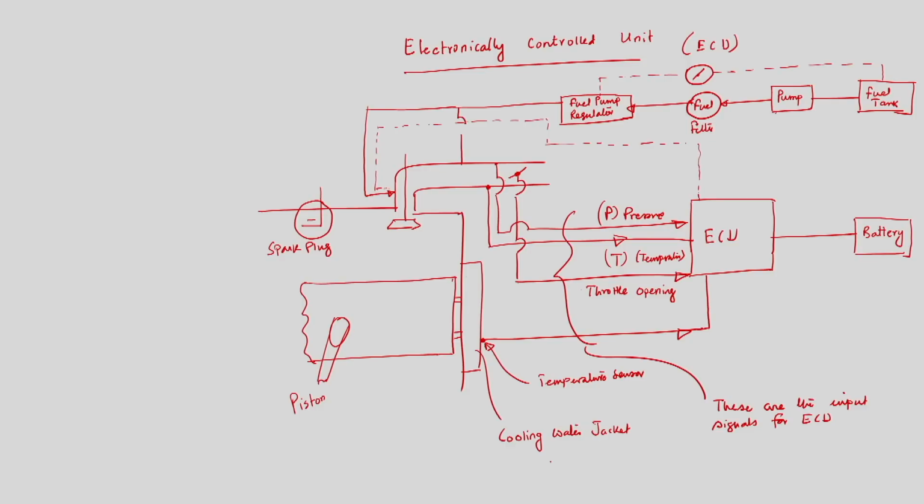Now, if you would like to supply fuel over here, again that information will come from the ECU. So, these are actually very important. What we have seen is that the amount of fuel that will be injected into the engine cylinder depends upon the load and also the pressure and temperature of the air at the intake manifold.